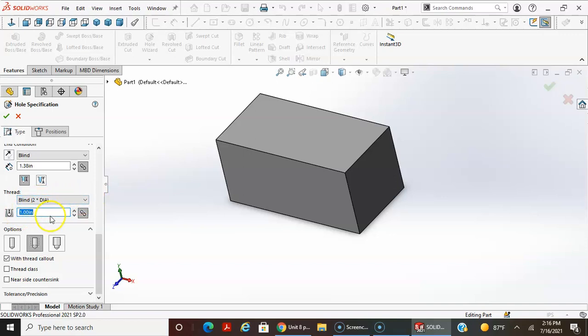the diameter. And then if you go deeper than twice the diameter, the clamping force or the holding force of the thread does not increase at the same rate as the depth of the thread.